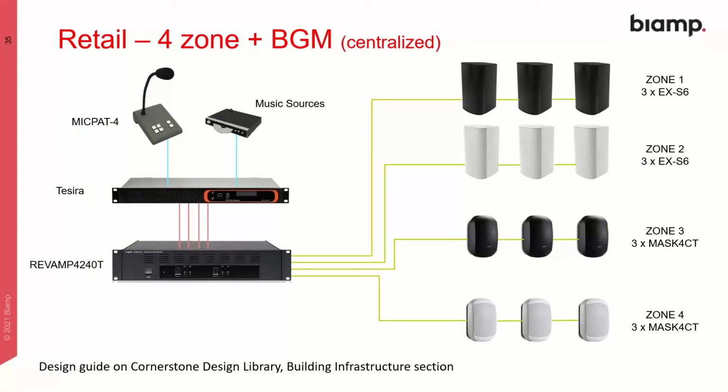So moving on to a slightly more complex 4-zone with background music system. So this is the centralized version of this. At the heart of this, we have a Tessera Forte in this case. It could easily be a Tessera Server IO, of course. So that is accepting an analog audio signal, plus 4 logic connections from the mic pad 4, directly into the back of the Tessera Forte.